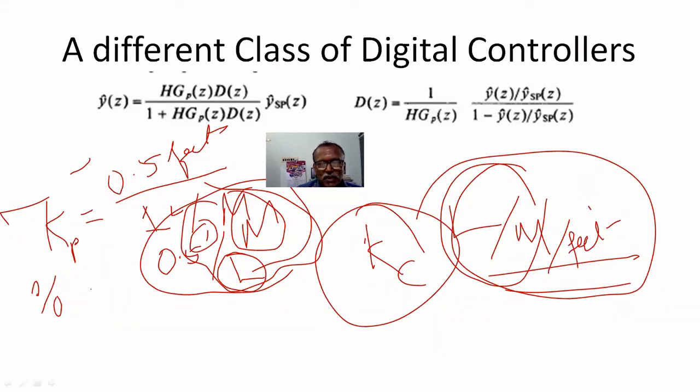Means its set point for a chemical engineer is 1500 degrees centigrade. For an instrumentation engineer, it is 50%. On the level process, of 10 meter height, it should be maintained at 5 meters always, because the total span is 0 to 10 meter. So 5 meter corresponds to 50%. For an instrumentation engineer, that also is 50%. Whatever the chemical engineer says, the instrumentation engineer may not be able to understand, but he must understand. But he should perceive as if he is a chemical engineer.